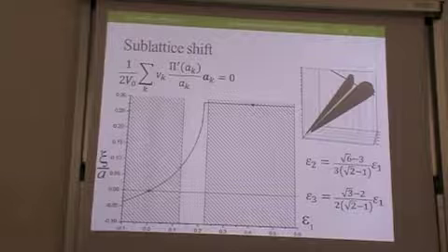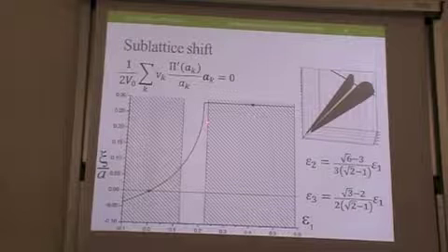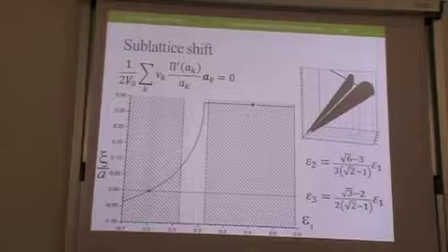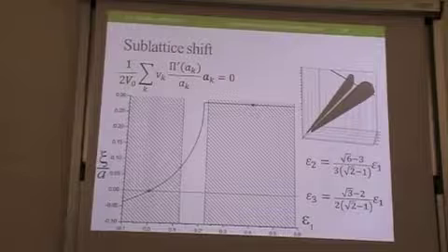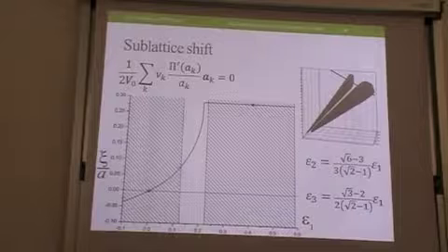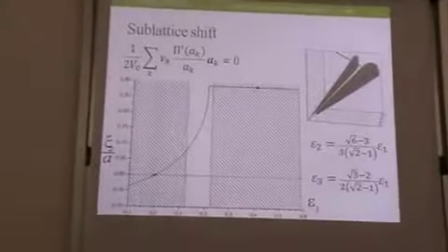We somehow stretch, and starting from here, near the border, the shift becomes constant. It means that two sublattices used to move along each other, and at some point they stopped moving along each other, and started straining all together. It means that the complex lattice really became a simple one. And somewhere here we get the stress-free configuration. That's what we see.